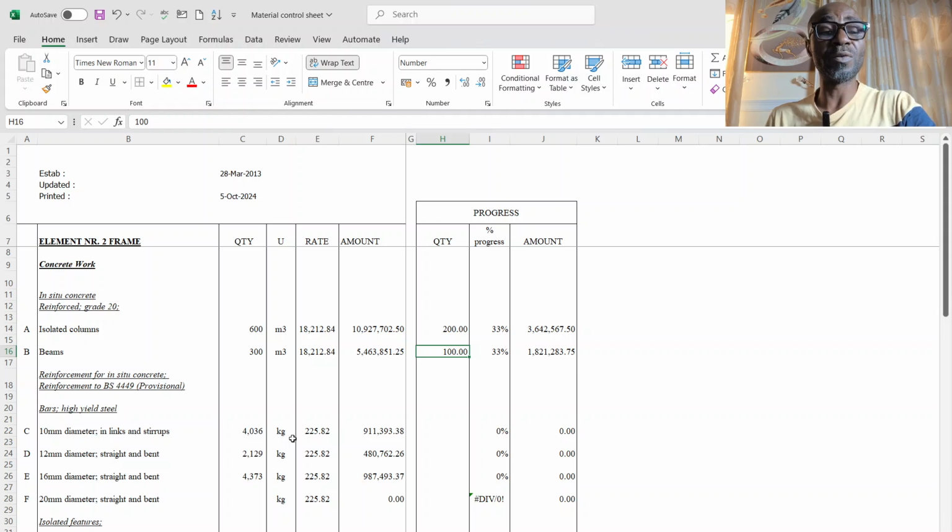And what you need to do is prepare a spreadsheet, and after getting these three informations on site, you're getting the progress that has been done in terms of quantity, volume of concrete that has been casted, square areas of plastering that have been done, and number of square areas of blocks that have been plastered. Then you get what the stock is on site. You get the quantity procured from the storekeeper or the procurement department. Then you can now go about doing your analysis.